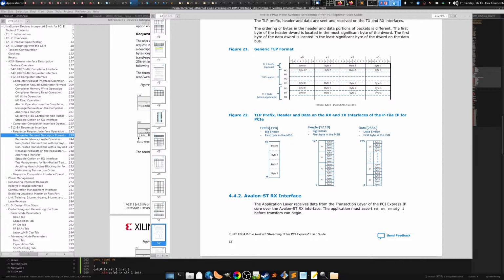So yeah, I'm working on the models for the various Intel FPGAs so that I can actually test this stuff, and then I'm working on porting the actual PCI Express Verilog code. Not there yet, but hopefully within the next, well, I don't want to give a time frame on this because I got a lot of balls in the air, if you will. But eventually, in the near future, I'm going to have Corundum running on both of these Stratix 10 boards, and as part of that, I'm going to have all the PCI Express stuff sorted out.